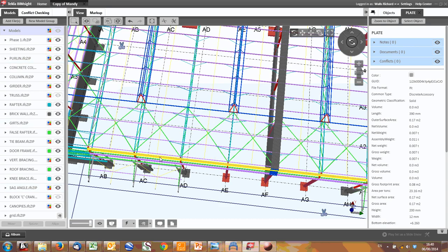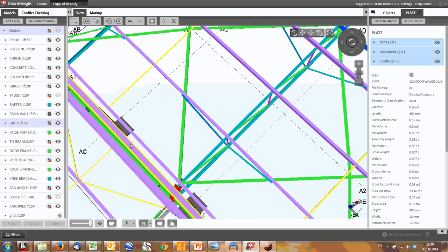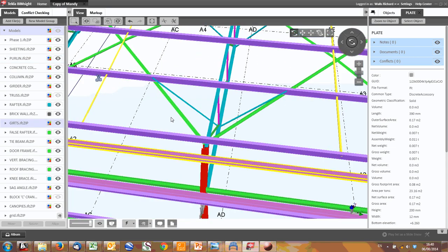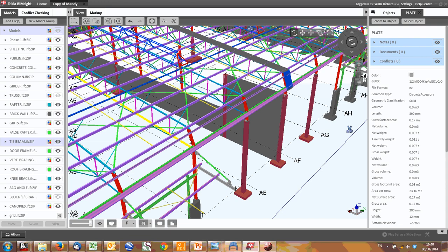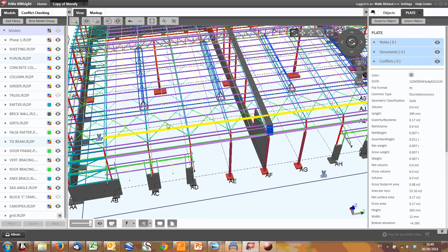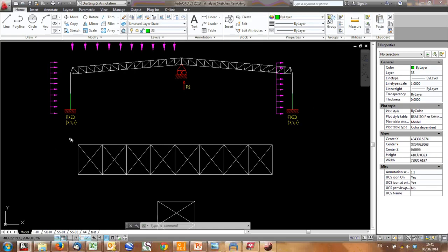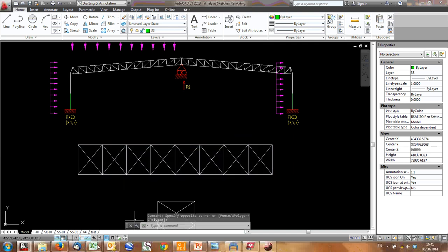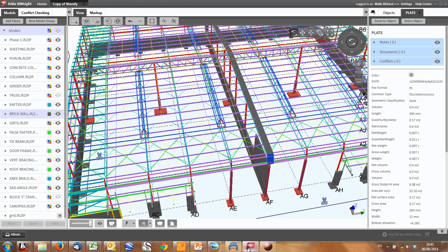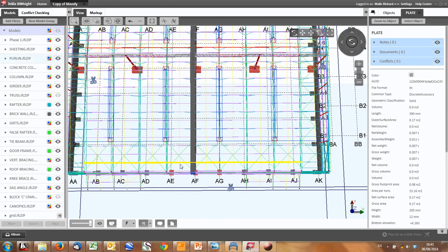However, to make sure this works, you've got to have something at the top, which is that blue pipe. There, and there's a pipe here somewhere. It should be, I think. And there's one there. And that then carries the horizontal loads, on the top and bottom. So I'm going to go back to our model. You can create a model that looks something like this, with the roof bracing that we were looking at a few moments ago. Plan. There we go. There's our roof bracing.